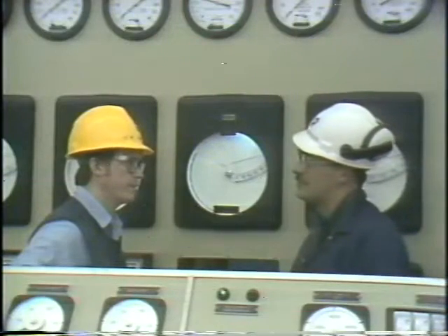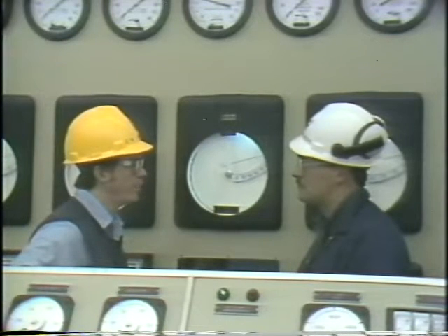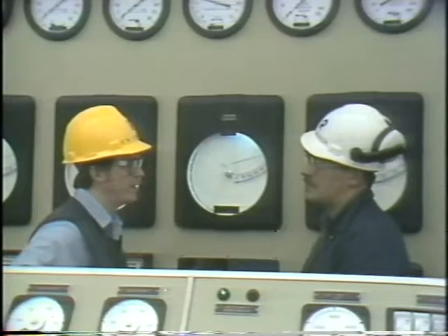If the operator on duty is the person who reported the problem, ask him how he first became aware of the problem. Find out whether an alarm had gone off or whether he just happened to observe the problem while he was checking his indications. See if the operator can also tell you whether the problem is a continuous one or whether it's intermittent, and whether he had to put the system in manual.